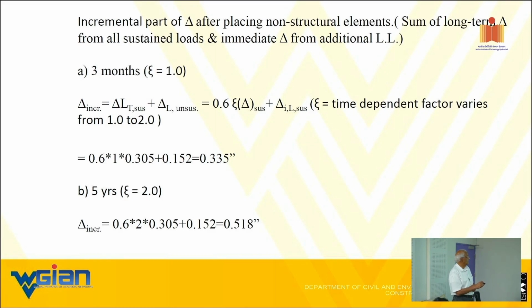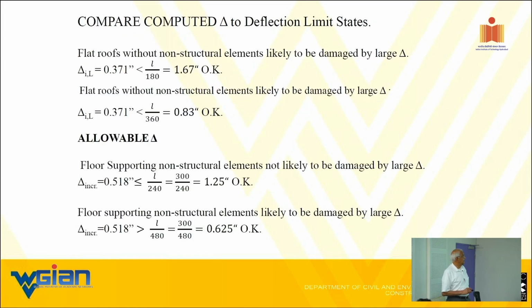The sustained load numbers. After 5 years, you can see how much the deflection has increased due to creep. Almost 50%, a little more than 50, but in that range. So the creep has a tremendous impact on limit states corresponding to the deflections. So that is my message.